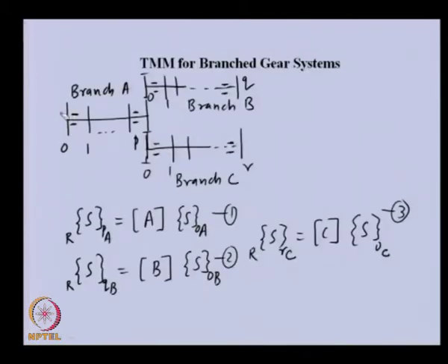So, there will be torque 0 here, displacement will not be 0, and for simplicity, because we are analyzing the free vibration, we are taking this particular station angular displacement as unity, and we will be obtaining relative to this what the displacements of the others are.